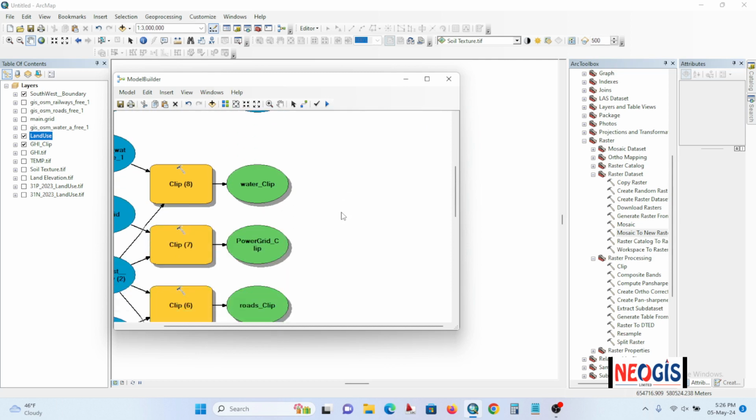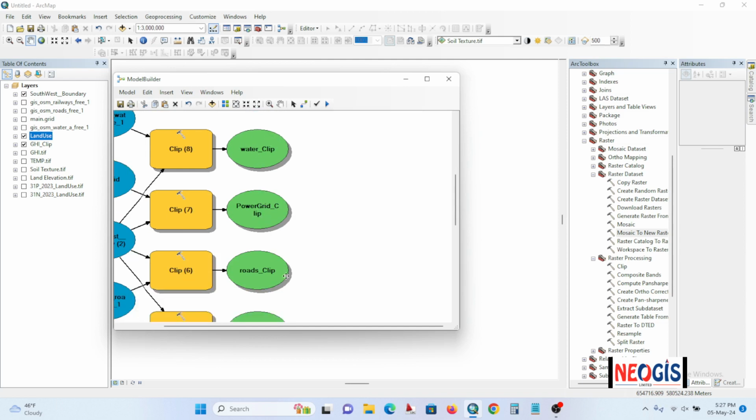The essence of projecting the coordinate system of this line feature is because the raster we are going to be working on has to do with the distance between each other, to enhance the reclassification of the raster. The analysis wants to define a boundary of reclassification, that is the most suitable and the moderately suitable areas. In order to maintain the standard units like kilometers and meters, we need to project it into a UTM coordinate system.